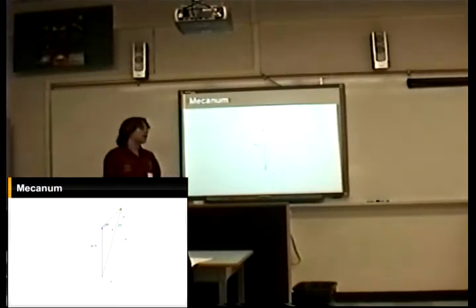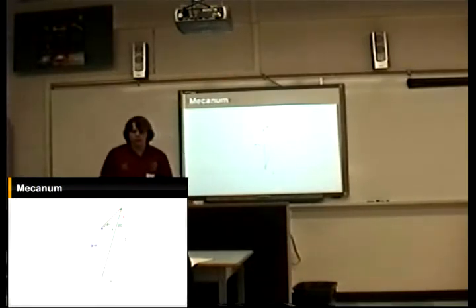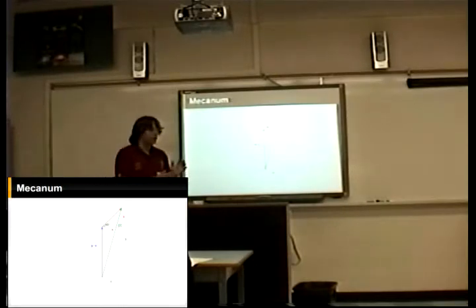So Mecanum wheels, compared to the other forms that you could do, are really, really simple to program. Conceptually, they are quite difficult, but in terms of the actual code you write, they're a very elegant solution. And if we were to make the rollers face the other way, which you need to do if you have a Mecanum drive, it's simply like inverting the x-coordinates.